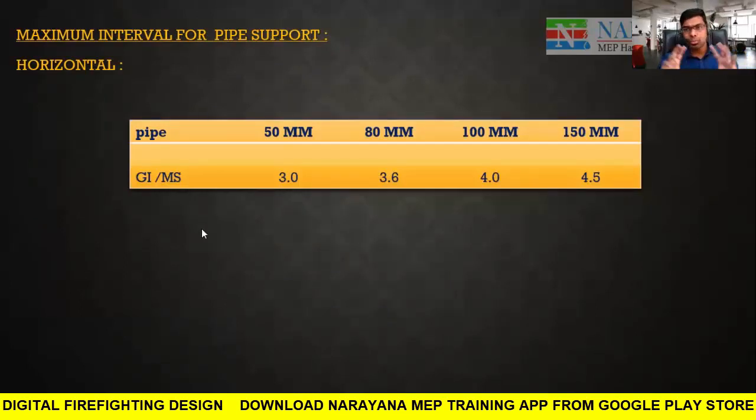Next is pipe supports. What pipe supports do we have? Horizontal, what is the distance, and vertical, what is the distance? For 50 mm pipe, the distance between two supports is 3 meters. For 80 mm, it is 3.6. For 100 mm, it is 4 meters, and for 150 it is 4.5 meters. This is the horizontal distance between two supports.